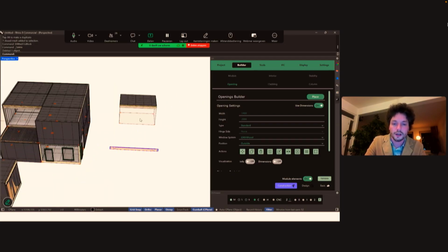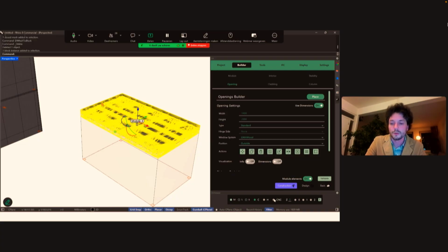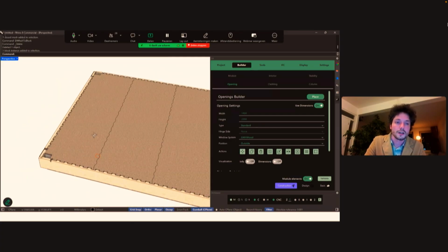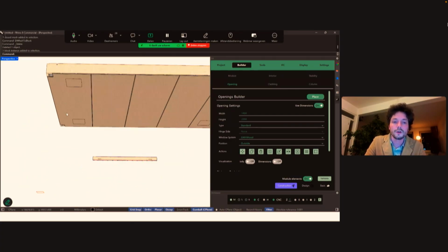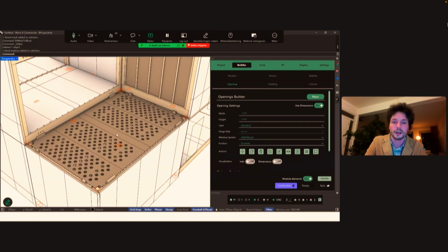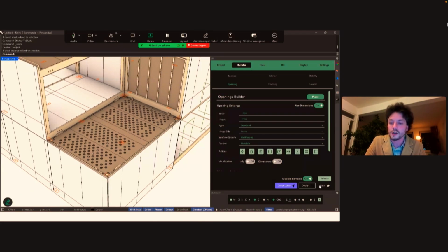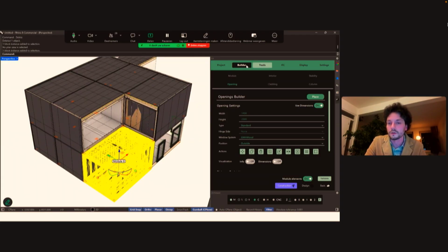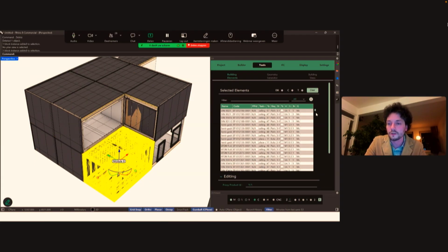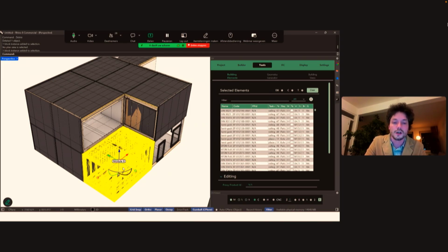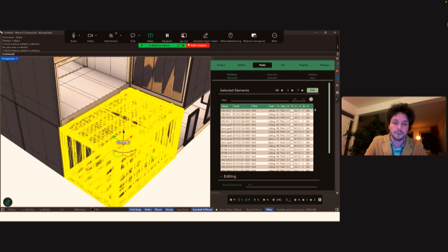As you can see now, we've created this new roof that has never been created before, but it has the same level of detail, with all of these elements that I just showed as part of it. This 3D model, with all of these elements that can be ordered from the factory, is a full description of the production that's necessary. In this case, there are about 2,500 elements in this module. Most of them are fasteners, and they're all labeled and described.